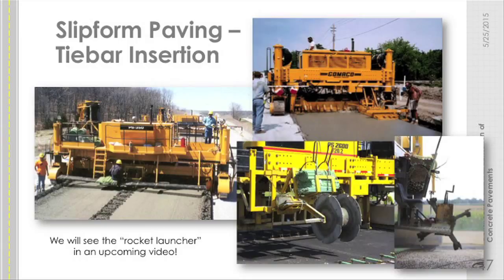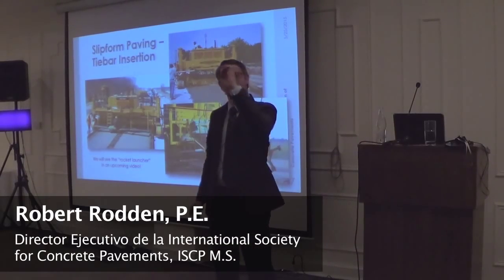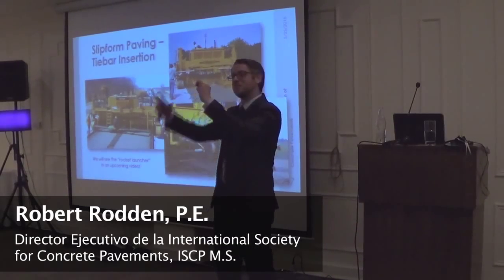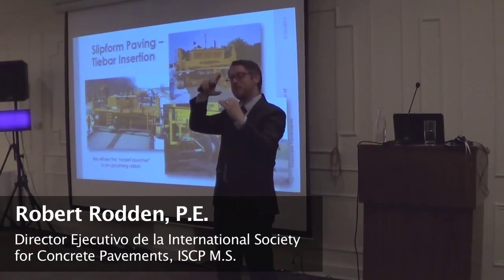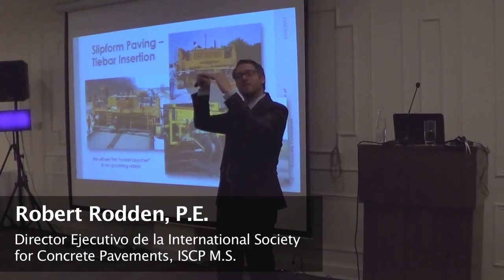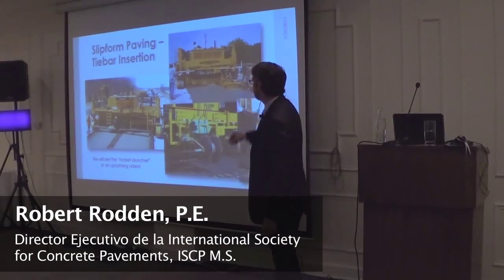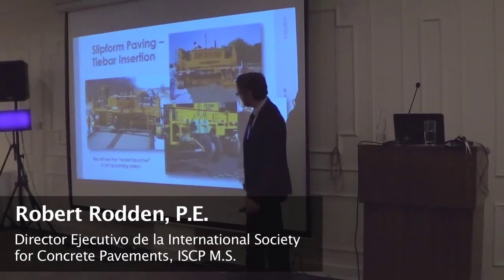This is a little bit more high tech. The benefit of this is that it confines the concrete. If you're pushing a piece of steel into a thickness of concrete, and that slab is confined on the bottom, when you push that in, it's going to push up on the concrete and leave a little tiny hump right at the surface. So this helps us prevent that action by confining the whole system.